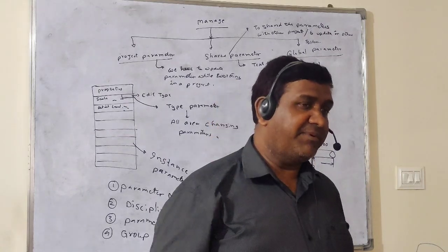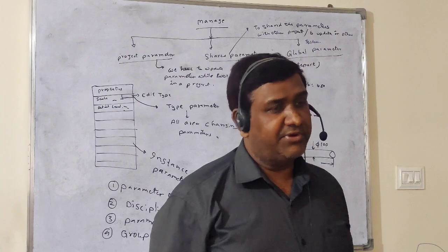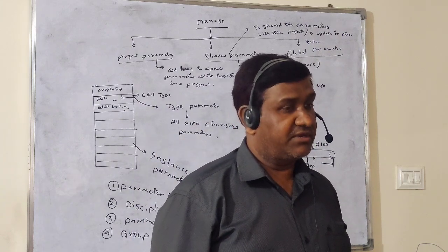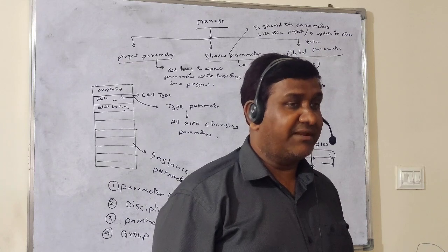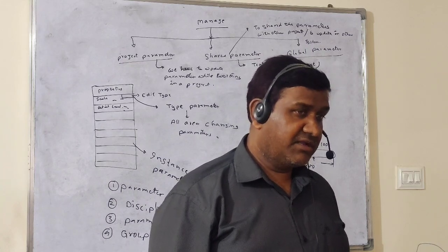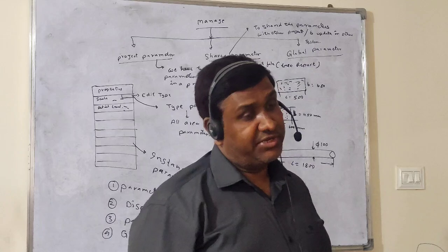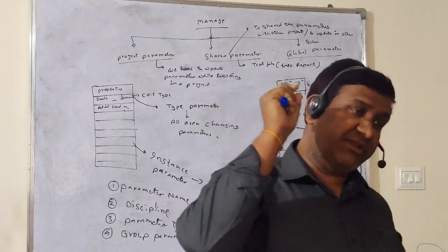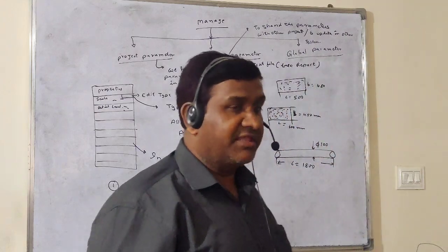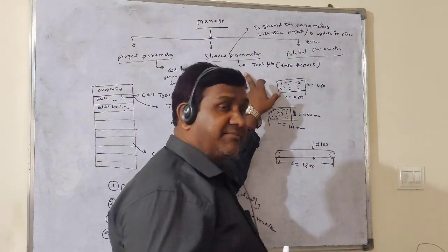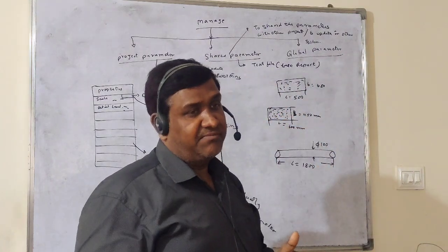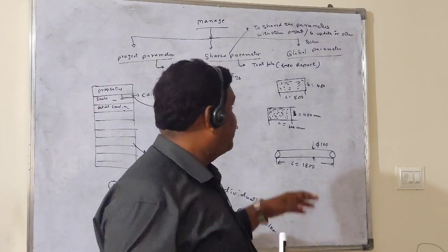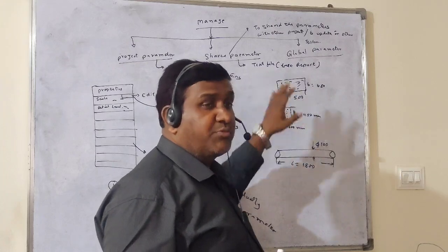And suddenly your PC has changed, your computer has changed, and you sit at another computer. What happens? Whatever parameters you updated there, the same parameters will not come to the other computer. But if you had created parameters as shared parameters and the system changed, the same parameters are recorded in a text file, like a notepad file.